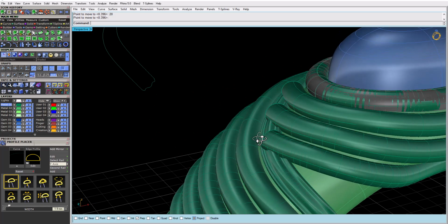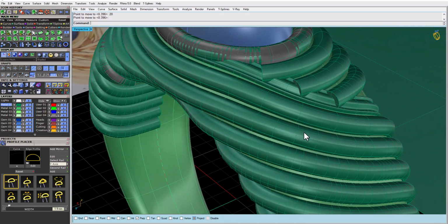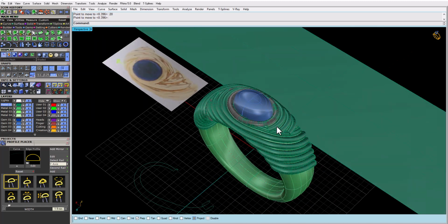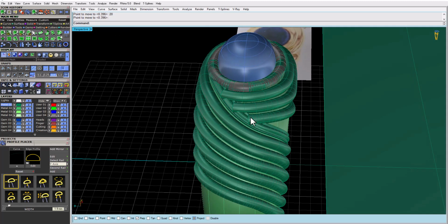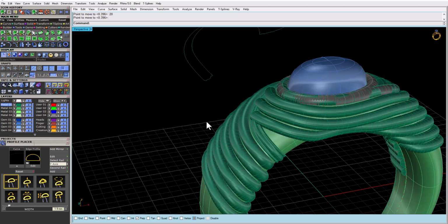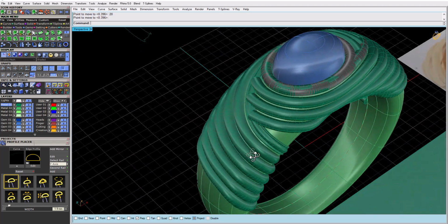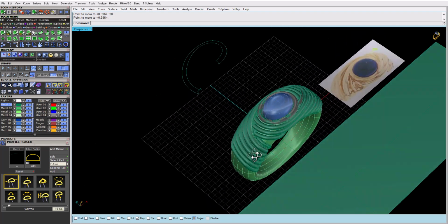And in case you feel like this profile is a bit tapering, you can do the pipe with two diameters. Okay, instead of one, you do two. You do like 1 mm over here, and then when it goes down, you can go like 2 mm. So it gives you the taper pipe. Okay, and once you have a taper pipe, you have a taper edge or the curve as a tool rail, and then you can do a sweep tool on it.